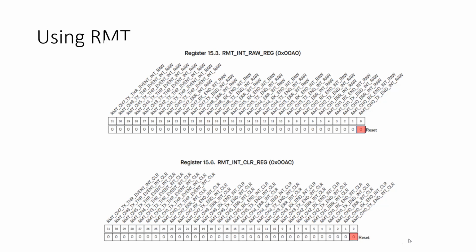done. Is that triggered after one sample, one PWM period? Is that how that works? Yeah, okay. There's one that gets triggered every single time. Right, so yeah, that's going to put a little bit more load on the processor because you're going to want to update that every sample at 8 kilohertz, right? Or whatever your audio file is.